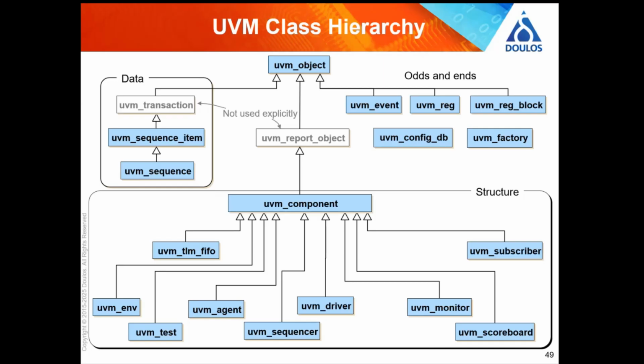So that class on the left there that says UVM sequence item, that's the base class for transactions. In other words, we're going to make transactions out of that. If you've not seen object-oriented design before, hopefully when you see the code, it'll explain it. You can see underneath that it says sequence. A sequence is a bunch of transactions.